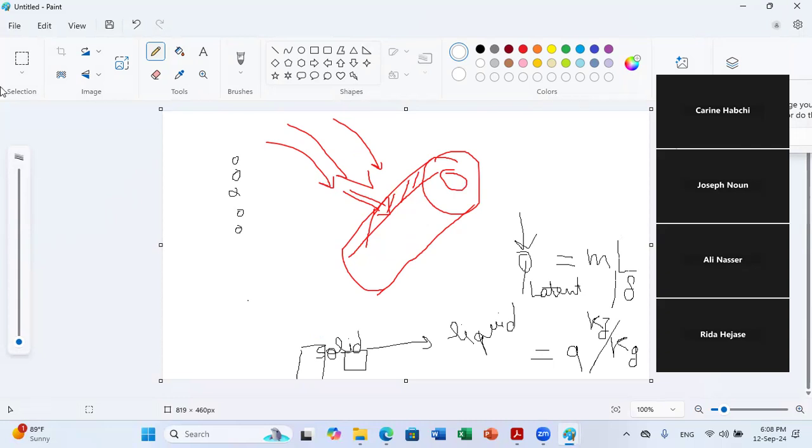Whenever you circulate water or any other refrigerant inside the tube, this fluid will capture the solar energy transmitted through your tube, and it will be convected by the fluid. Then the water that passes through the heat exchanger will be heated, and it can be circulated through a system for heat distribution.